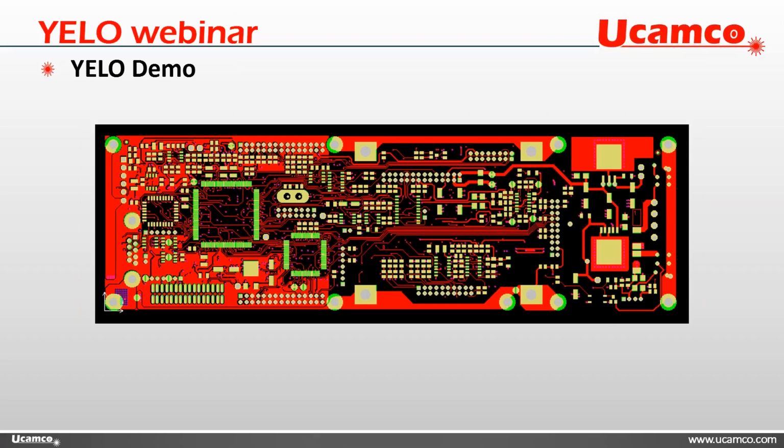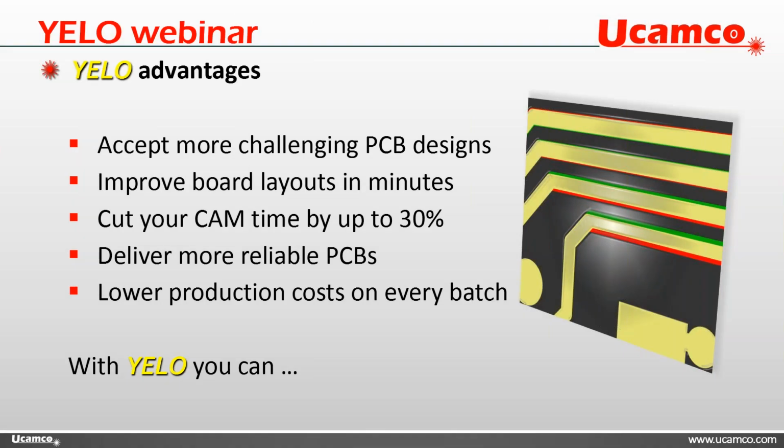So we had now a little demo of YELO, and I hope you liked it. So very shortly, what are the advantages of YELO? What I already talked about is you are able to accept more challenging PCB designs. If you always said, I cannot go below 100 micron, well, try now to get boards that are 90 micron and fix them up so they are actually 100 micron and make yourself and your customer happy.